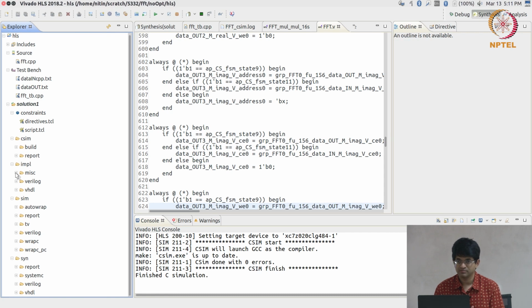And think about it, it is not at all obvious that that is actually happening, because what you had originally was a C code, and now what you have is a Verilog code. What proof do you have that they are actually both doing the same thing, except for the fact that Xilinx basically gave you some assurance that their compiler works? The unfortunate part is there can be situations where the compiler has bugs in it and actually generates Verilog code that does not work the way that you expect.